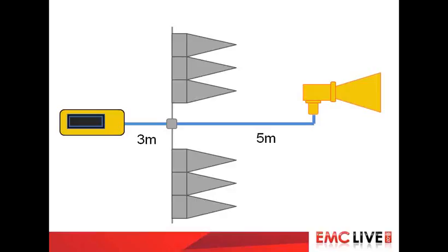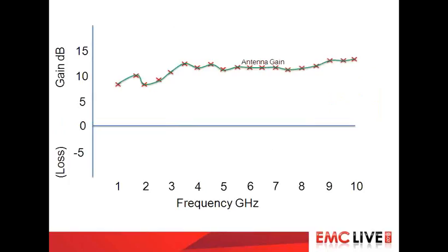Those are reasonable numbers. So I alerted you earlier that, particularly for me, and I recommend for you, is to make things visual so you can see what is happening with the system overall, all the way from 1 to 10 gigahertz. And this is particularly important because you want to be looking for any suckouts whereby misfortune, a dipping gain in the antenna happens to coincide with a high loss, high frequency cable loss, and by visualizing it, you can see immediately if you're going to hit a problem early on.